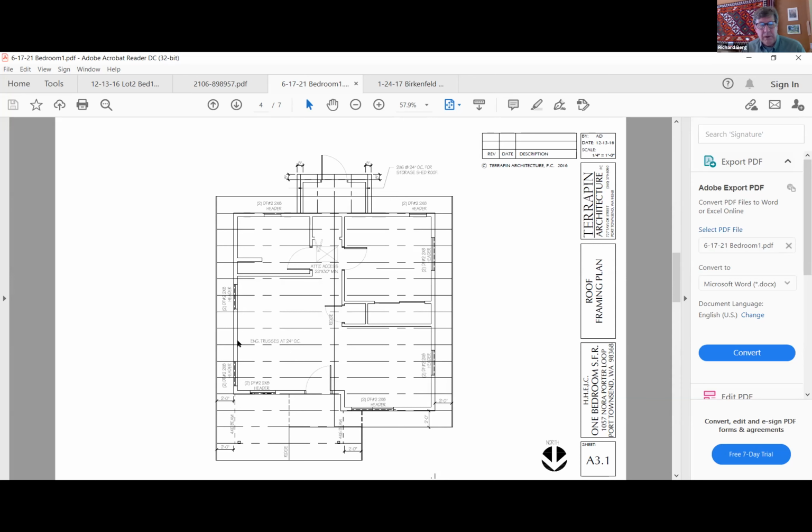That pretty much means that when it comes time to build this, the builder would just order the trusses from the lumber yard, and the lumber yard would order them from a truss company, and the truss company would provide the engineering design for the trusses. So the specific engineering of these trusses doesn't need to be addressed in these plans. I mean, that engineering information from the truss manufacturer will want to be included with your package on the job site. Right.